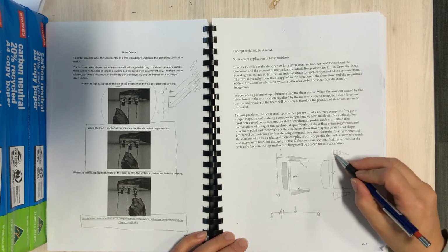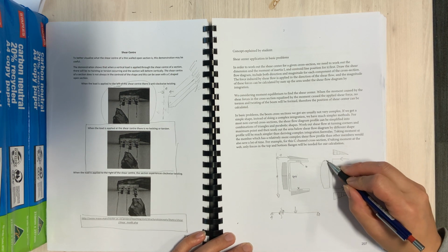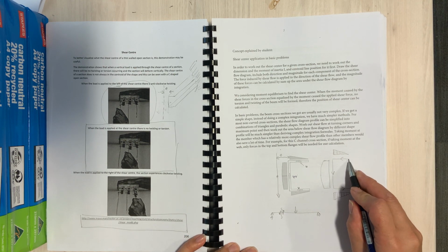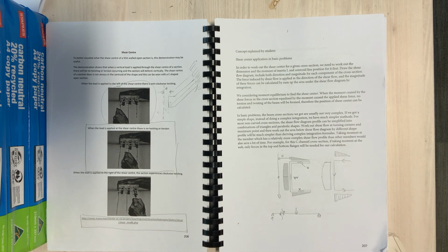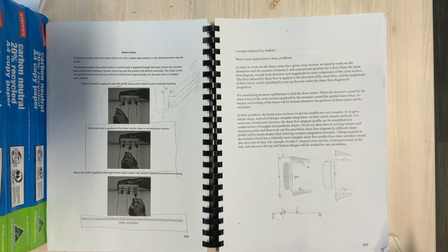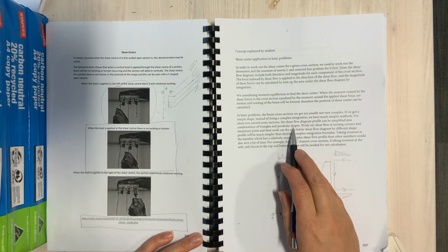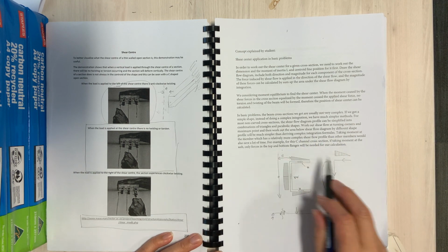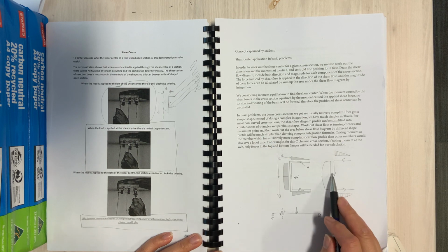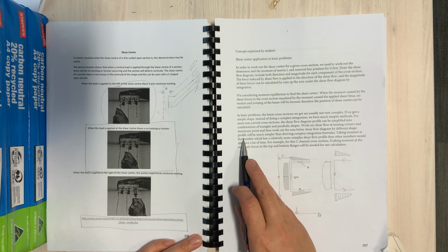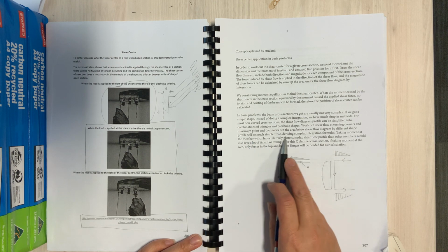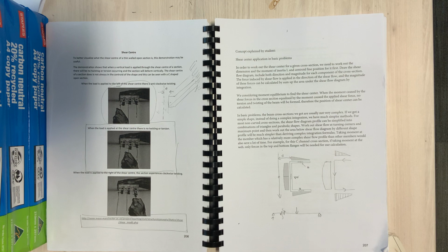So we know from the shear flow that the value of the shear flow Q1, or Q at the corner, must be equal to that, and the reason why it's called flow is because you can think of this as being a pipe with water flowing down through the system. So work out the shear flow at turning points, so that would be a turning point, and maximum points, and that would be a maximum point. Then work out the area below the shear flow diagram by taking different shape profiles, and that would be much simpler than deriving complex integration formulas.